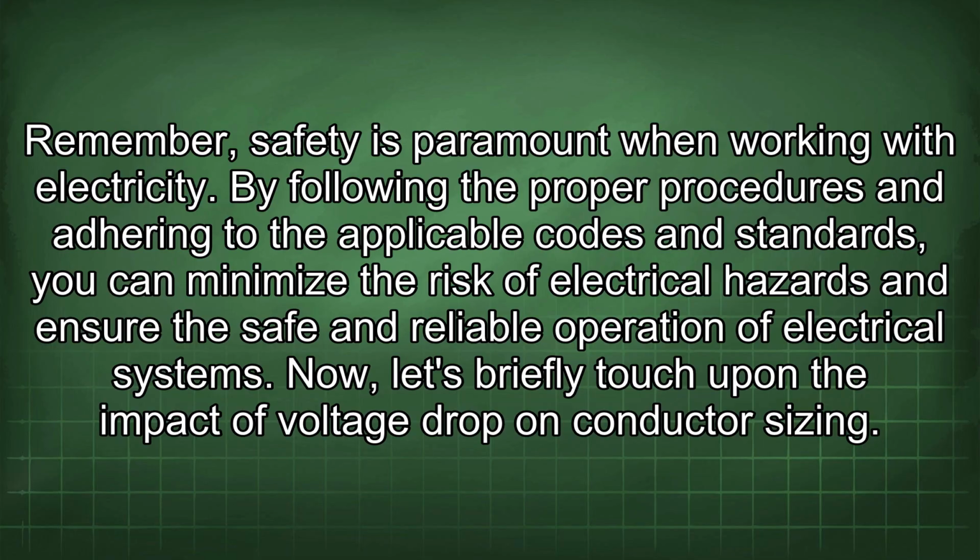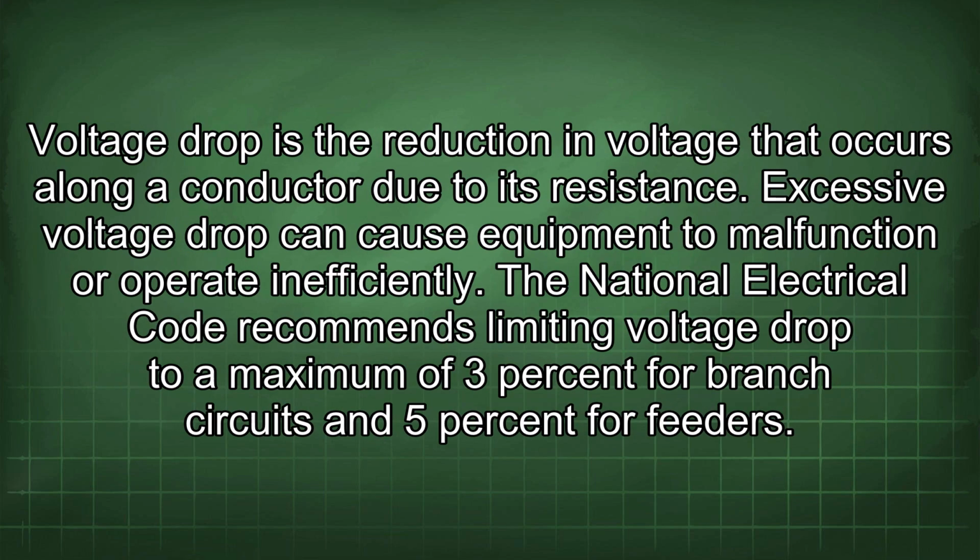Now let's briefly touch upon the impact of voltage drop on conductor sizing. Voltage drop is the reduction in voltage that occurs along a conductor due to its resistance. Excessive voltage drop can cause equipment to malfunction or operate inefficiently. The National Electrical Code recommends limiting voltage drop to a maximum of 3% for branch circuits and 5% for feeders.